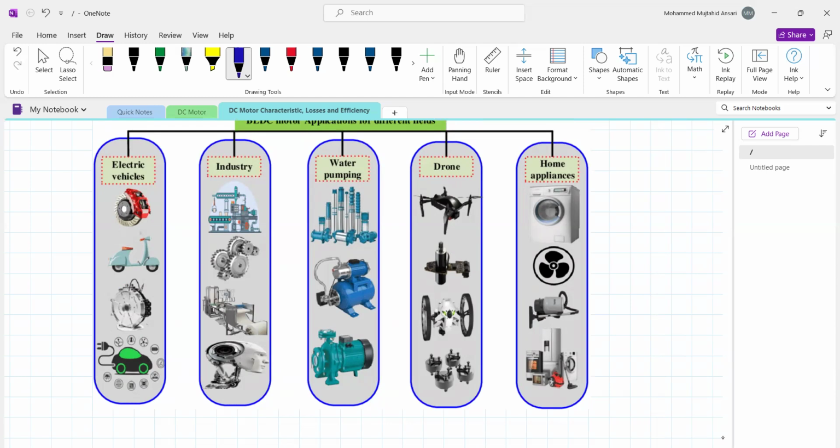Now we are using BLDC fan instead of the regular fan. We are using brushless DC motor fan whose power consumption is hardly 27 or 28 watt as compared to the 60 or 70 watt of our regular fan. Similarly, our lamps are now LED lamps which work on DC, as do our laptops and computers. So nowadays, because of more and more small household applications moving toward DC supply, the DC microgrid is more popular.